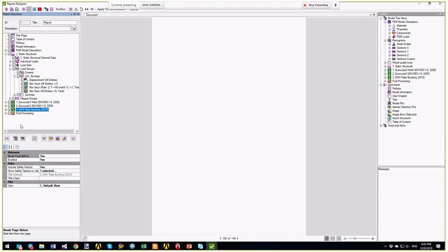So I would like to make a conclusion that in 30 minutes we set up our combinations envelope and fatigue group. We did recognition of weld and buckling plate fields. We added 3 standards. You saw there were a few options to define extra settings to do the calculations, and to estimate the results. You had to add 3 plots for each standard, and that took us around 30 minutes.